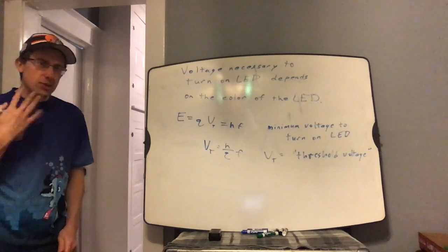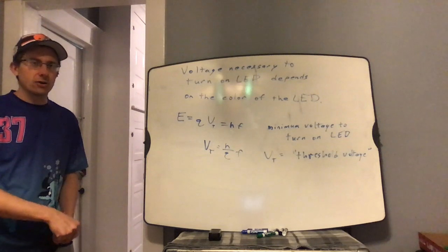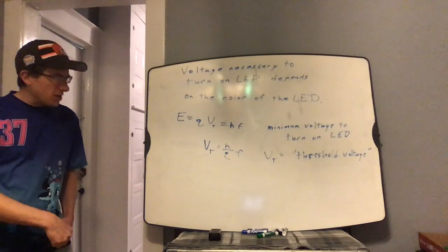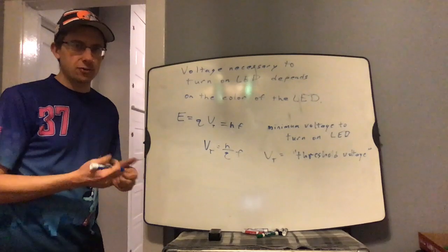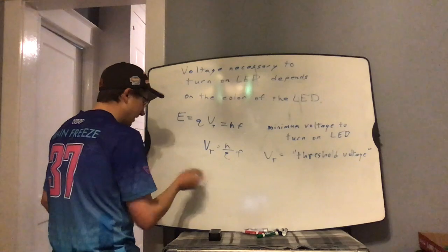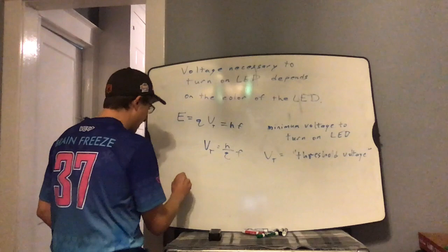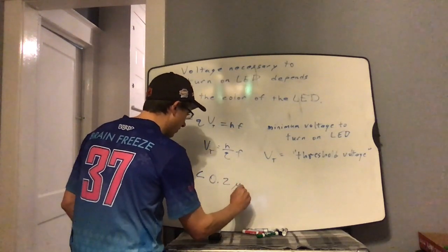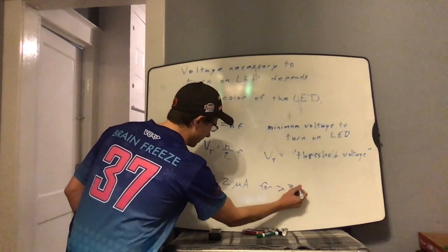Now, the very last complication. The multimeters we are working with are very cheap. They are less than $3 each. So measuring 0 current in a multimeter is not really going to be that accurate. So instead what we're going to do is presume that instead of saying it's 0 current exactly, let's say the current is less than 0.2 microamp for more than 30 seconds.